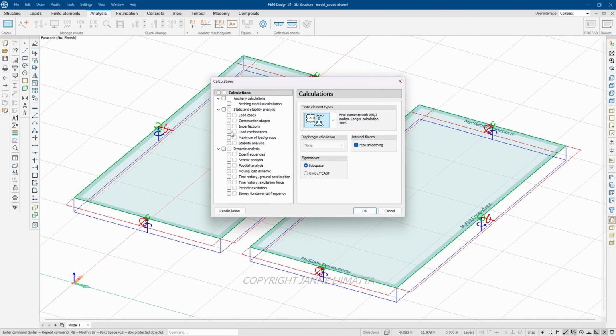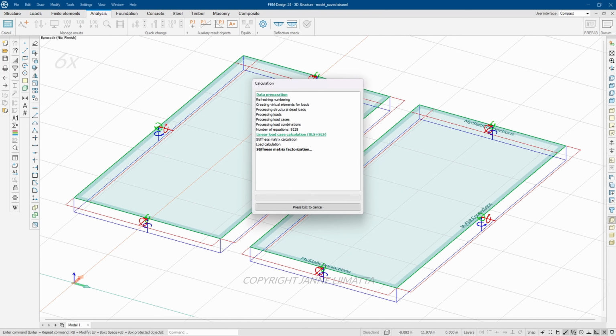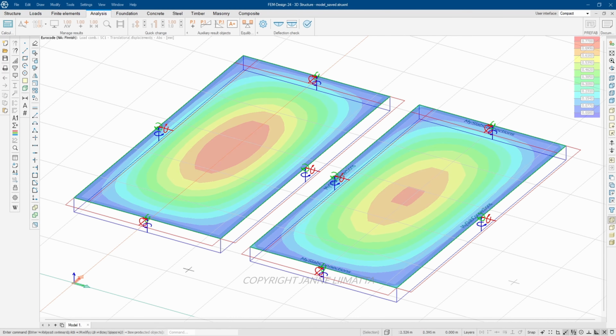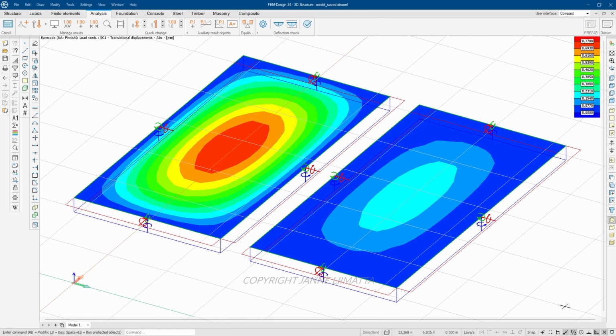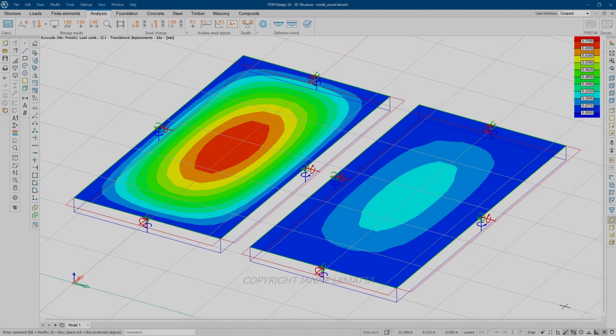I will run the plastic analysis. By navigating to results, it can be concluded that the plastic limits for rotations have been exceeded, and the slab now deforms more like a slab with hinged edges, even though it was defined as fully rigid. Here are the deformations for the rigid edge connections as a refresher.